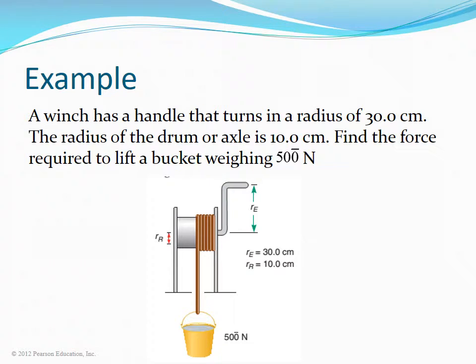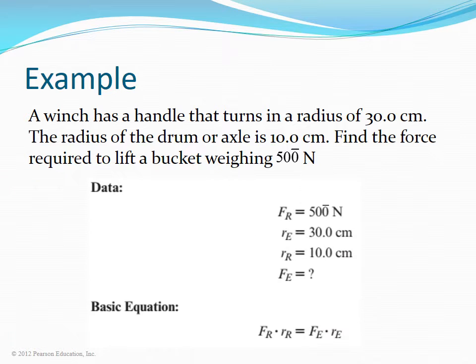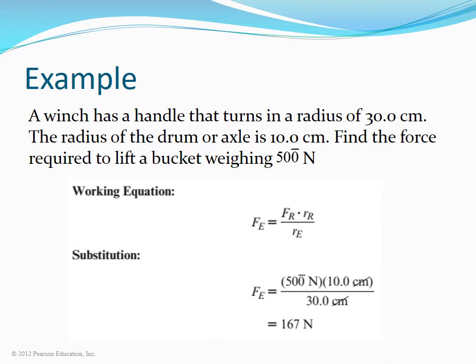First, sketch the problem. Write down what we know and the basic equation. The working equation solves for the effort force. Substituting what we know gives an effort force of 167 newtons.